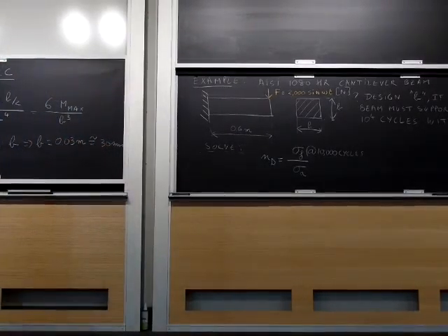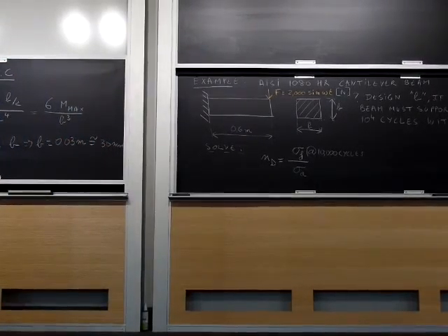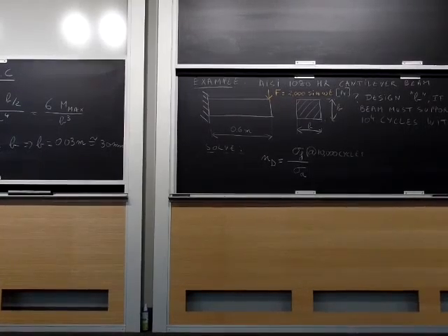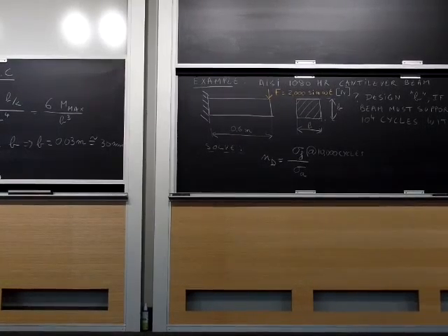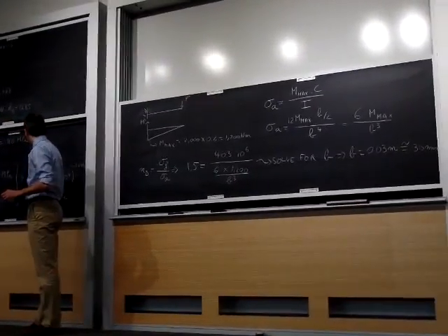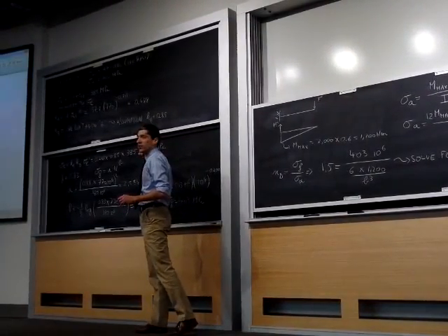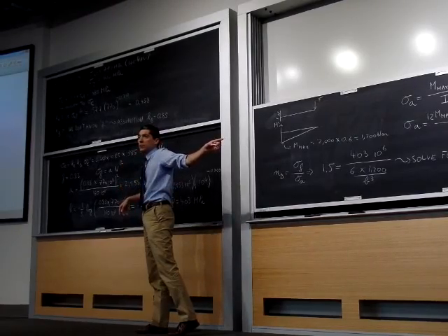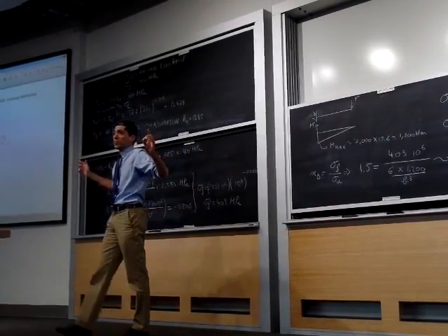Where do we use the strength to calculate the 160 MPa? Where does that come back into play? That wasn't the fatigue strength, right? Or sorry, the endurance limit was 160, right? That comes into play when calculating our fatigue strength. So we find a value that is larger than the endurance limit because we're only needing 10 to the power 4 cycles, not 10 to the power 6, which is the equivalent of infinite fatigue life.